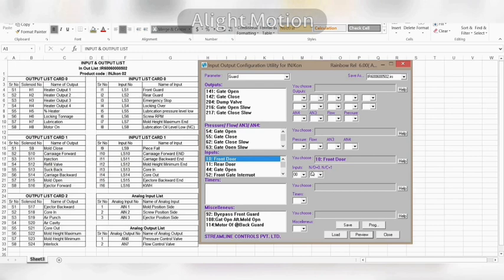If you have selected NO0, then our input will be NO to NC. If you have selected NC1, then our input will be NC to NO. You can make any input NO or NC. All our inputs in the wiring list are NO inputs, according to the configuration of our machine, such as our front guard and back guard are NO inputs. So now, in the inputs, we define the front door as number 1 input with NO0, and we define the rear door as number 2 input with NO0, and save.